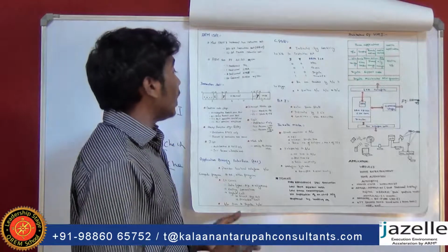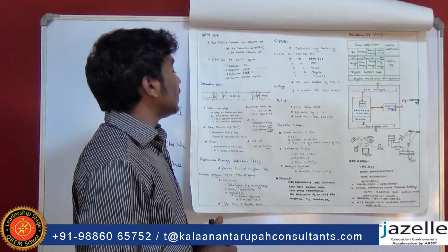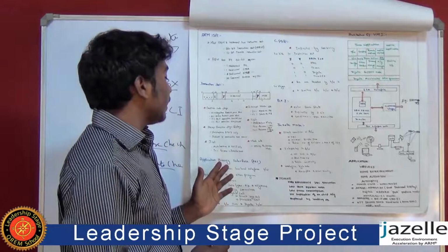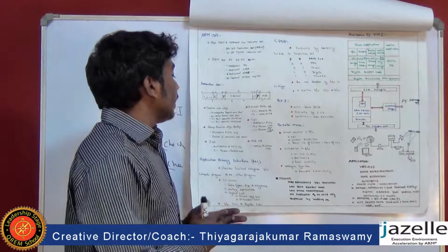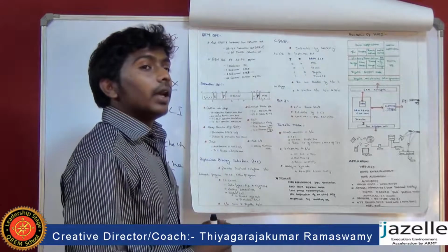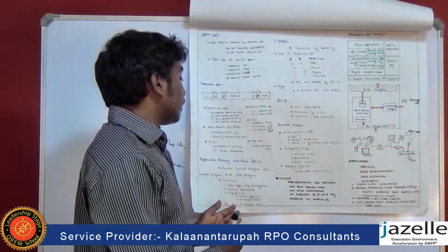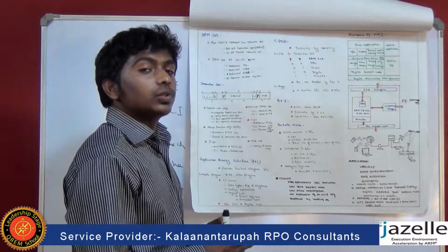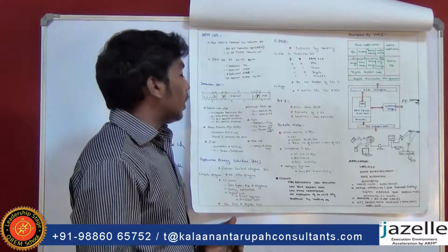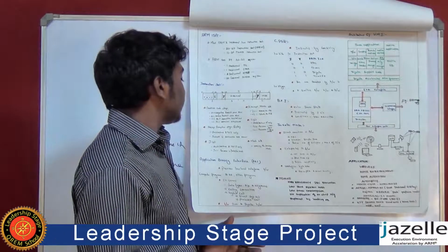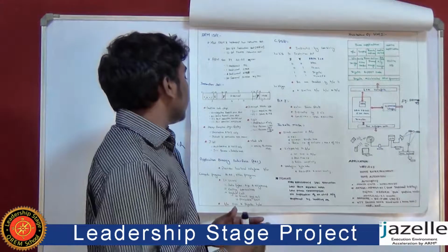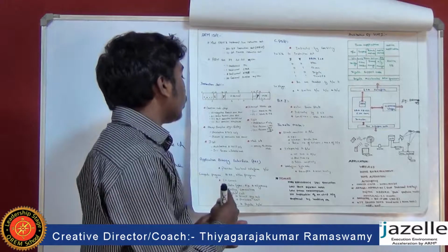They are not defined. And the next single bit is the J bit. It is used in architecture 5TEJ only, and if it is set to 1, the processor is in Jazelle mode, that is used for compiling the Java bytecode to machine instructions.